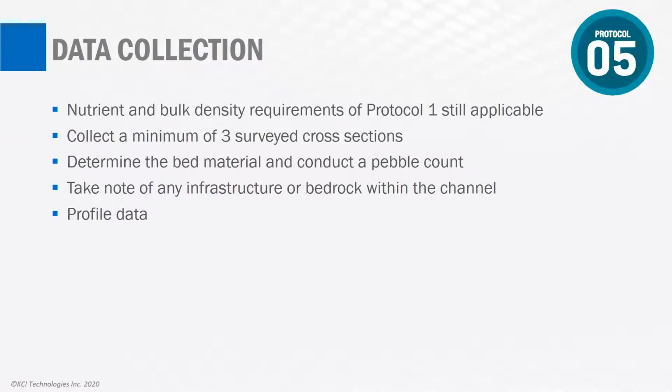So I'll show each of the equilibrium slope equations, which hopefully will make a little bit more sense. You should also take note of any infrastructure or bedrock within the channel that's not subject to erode. And then having profile data helps indicate the existing slopes.